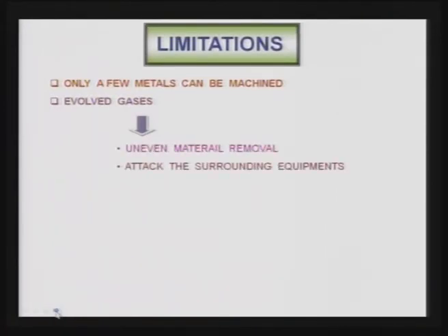It will lead to uneven material removal and attack the surrounding equipment. That is another point one has to keep in mind, that whatever gases are evolved, they should be exhausted from the area where this chemical machining process is taking place, because this will attack the equipment surrounding the chemical machining setup.